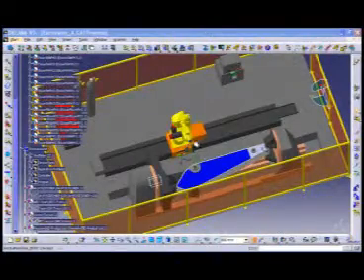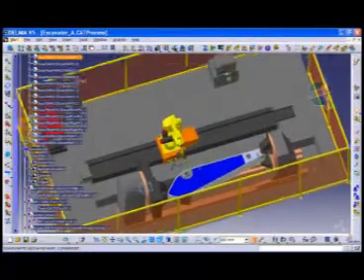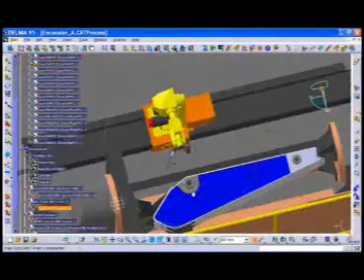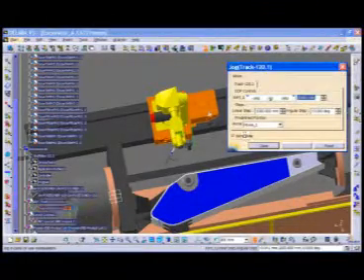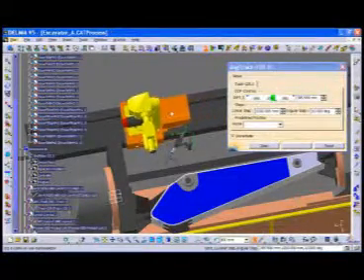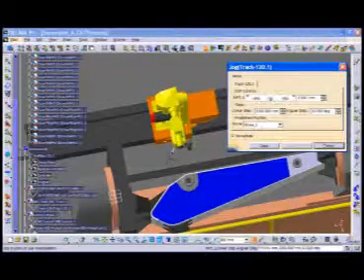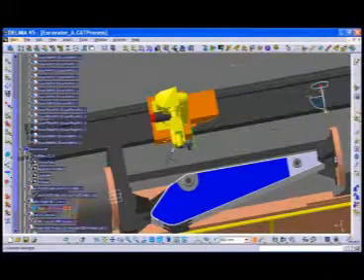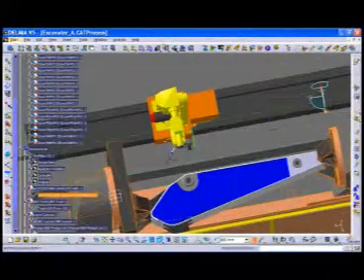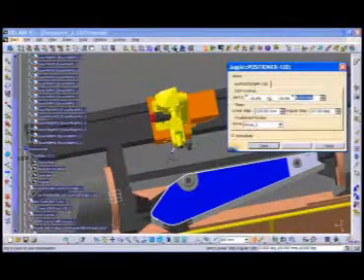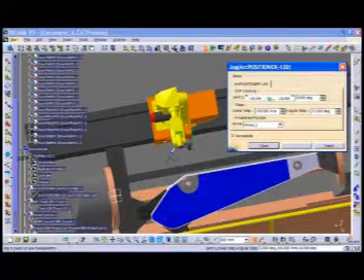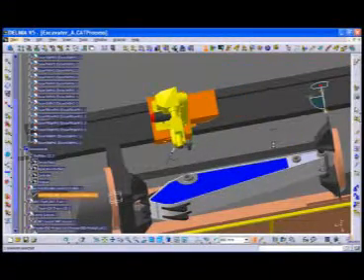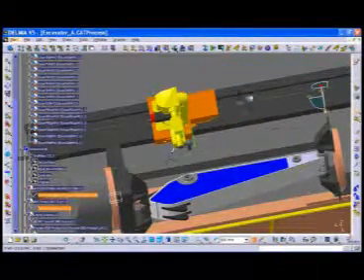Today, most robotic arc welding cells use a part positioner, a gantry, or both for production. These devices allow the work cell to be flexible enough to do a series of welds. They also allow for a variety of parts to be welded. The trouble is when the robot programmer has to manually program these three pieces of equipment. Manual programming is complicated, not to mention programming the work cell using a teach pendant can be very time-consuming.